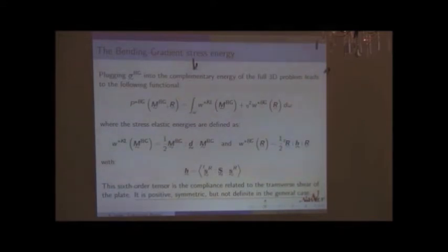Okay, so I have a constitutive equation. I have a strain energy density, with the Kirchhoff law contribution, so the bending contribution is there, and you have the shear contribution, which is properly scaled. This is a plate strain energy density, because it's directly defined on the midplane of the plate. All right, so I'm happy, but if I want a plate model, I need equilibrium equations.